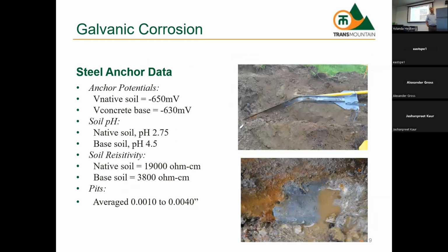You check it periodically. You check it every year. You take a potential on it. The potential, again, a magnesium anode sits at negative 1.7 or 1.75 volts versus copper sulfate. So every year you're going to go out there and check the potential of the anode. When it starts dropping, like 1.4, 1.2, now you know it's being consumed, so you have to replace it.